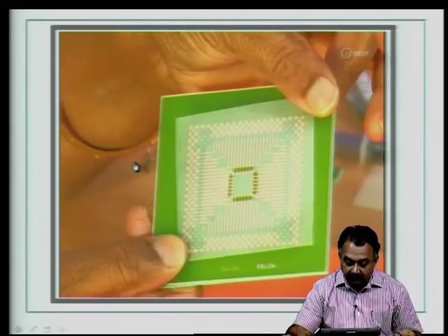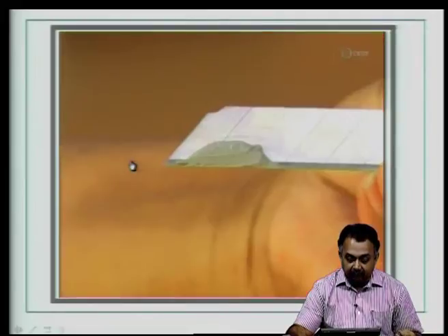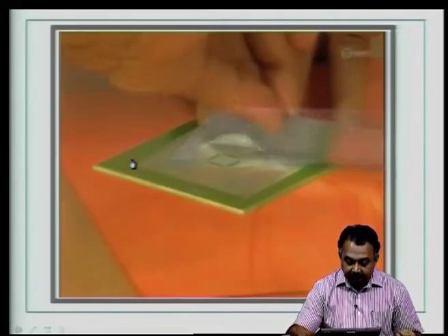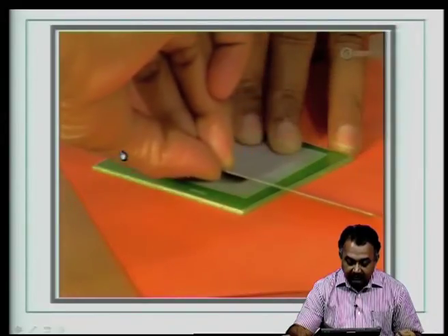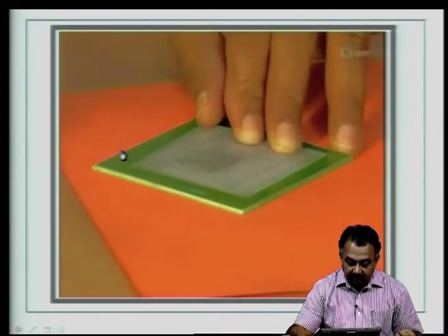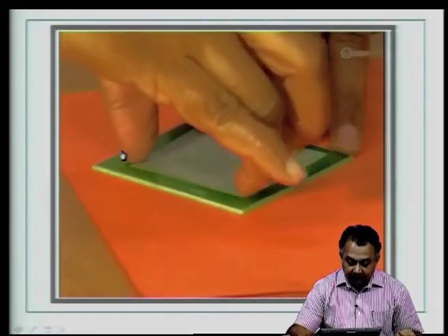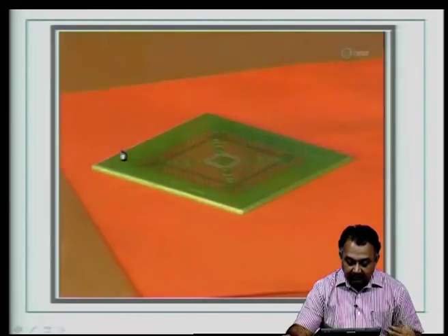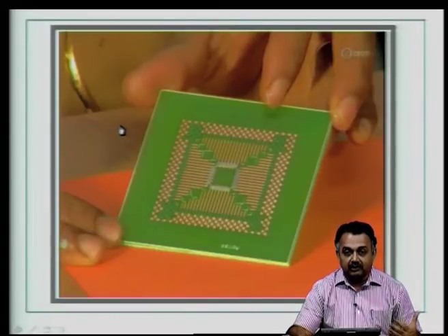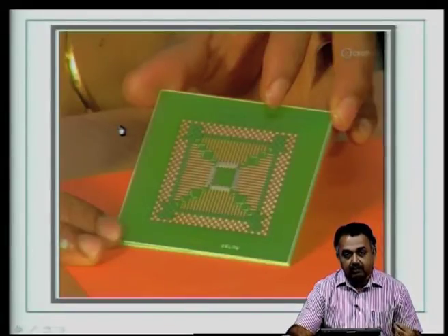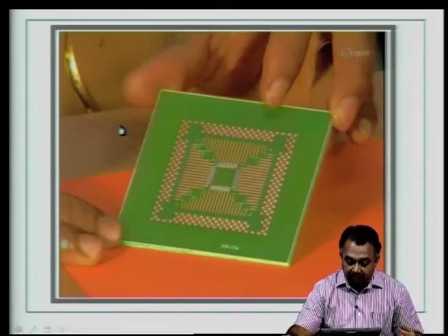It is now aligned with the component footprint on the substrate. Now, use a squeegee and then squeeze the solder paste through the stencil material. If you have a proper stencil containing a large number of such prints to be done, then it will be a huge stencil. Here we are talking about a very small board size that needs to be printed.